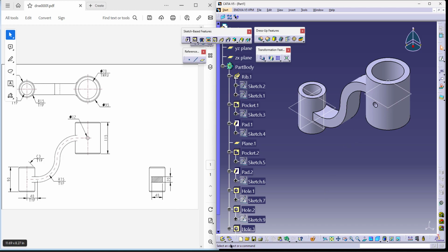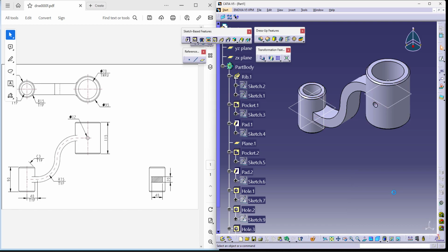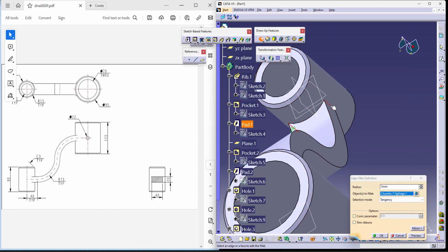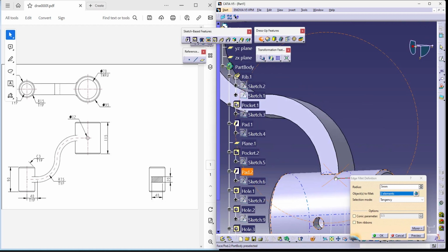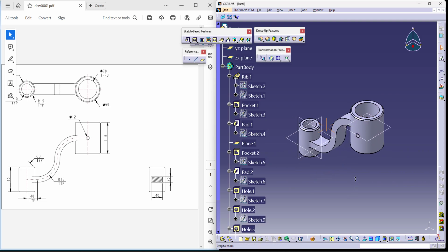Now, we can continue with the chamfer operations. You can use chamfer, the first, the second. I'm selecting all 4 in one because it says TYP. That means all 4 have the same type of chamfer. I'm using 3. And I have rounds which is R15 on all the 4 sides. Again, since it said typical, it has the same on all the 4 edges. Once you go back into your isometric view, this will be your model.